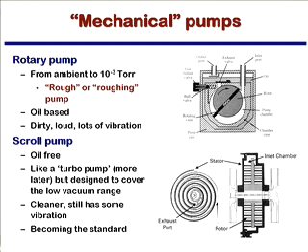And then the other use of the roughing pump is often it sits on the other side of, say, a turbo or a diffusion pump, one of the higher vacuum pumps, and is used to back off and remove the output of those pumps out to air, okay? So it forms part of a system in that regard, and we'll see how that all goes together.